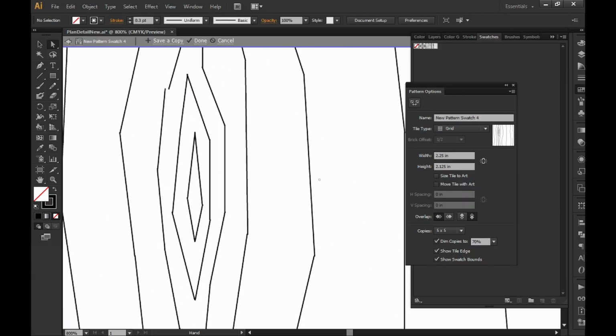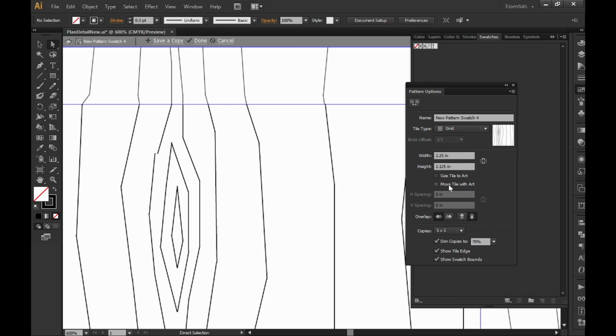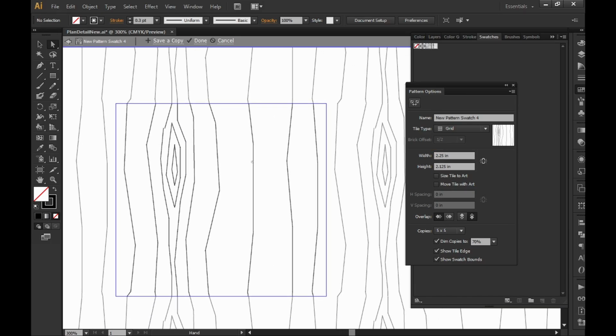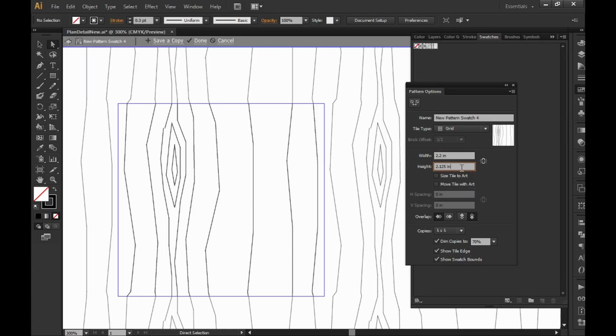and then you can even shift, like 2.25. I can shift it horizontally if I wanted to, like maybe the width of the swatch is not that big, maybe it's 2.2 instead. You see how things shift over? So you can shift things over if it's not lining up perfectly, or you can even change the grid, how it tiles, like a brick, or a grid, or brick by column versus brick by row. So it's really up to you how you want to make things seamless.